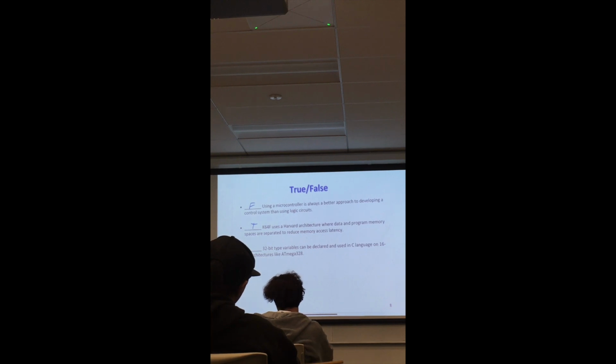Okay, because long integer was needed for 8-bit architectures, 1-byte architectures. So for 1-byte architectures where we were processing only 8-bit numbers, the C language was declaring that information as byte, referring to integers as bytes, right? So integer, 1 byte. Long integer was 16 bits, or 2 bytes. Long was 32 bits. So that's why we have these kinds of conflicts with long, and so on and so forth. So that's one. So 32-bit type variables can be declared long.